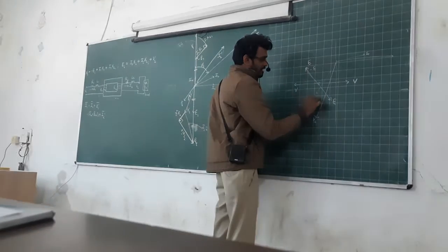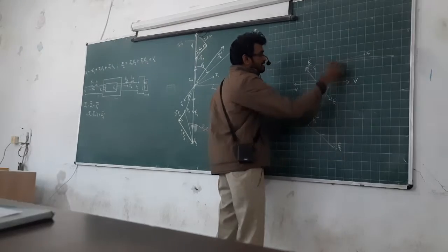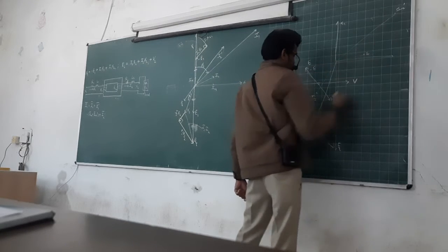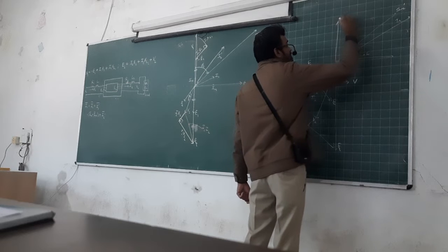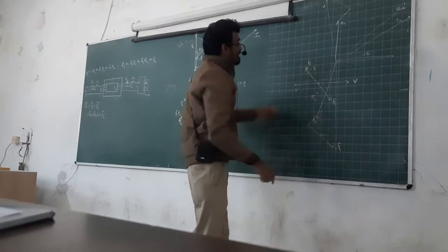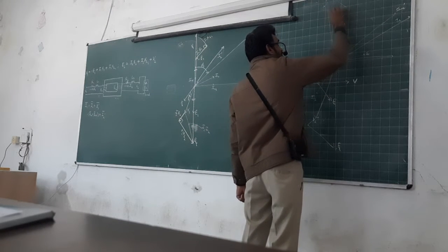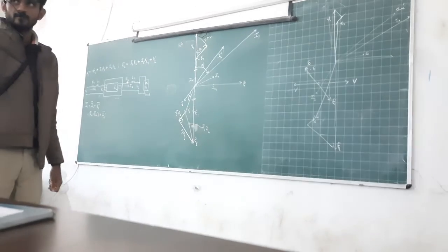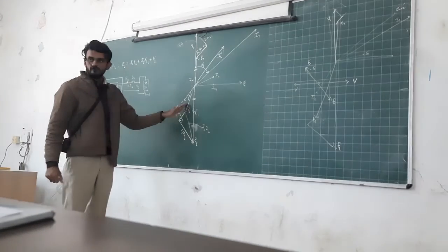And then here I2. And then we will add two vectors. So here it will be E2. And then there will be E1. And then I0. I0 will be added to I2 dash. I2, then I2 dash. Then I will add those two. I will get I1. And then I will add here I1 R1. And here I1 X1, and then I will add here V2. So V1 then becomes smaller than V2, almost. Or for that, these losses are small, then I have to make scaling. This is smaller and this is also smaller. Then it will become a scale diagram, almost near to scale. Okay. Then the vector V1 will be smaller than V2. Otherwise, the vector here is larger than V2, but that is quite okay.